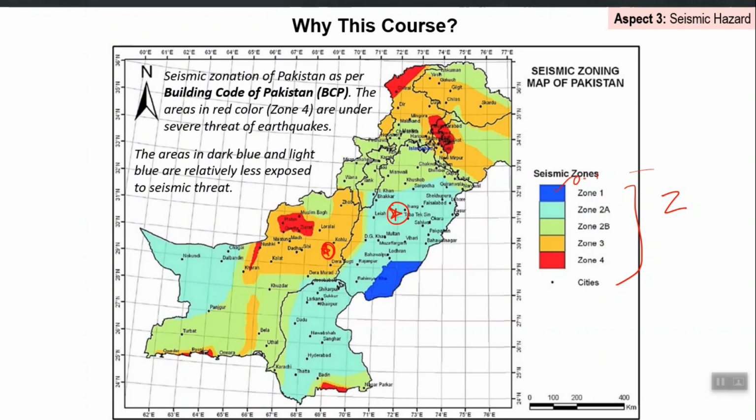So you will have a clear picture, and ideally your point is correct that we need that historical data. That whole process is based on the processing of historical data, which becomes the basis for future forecast. If you simply correlate this map with the faults and all the seismotectonic features, you can guess that there will be a fault here, and a fault here, because all the historical seismicity we convert into future forecast, after all that statistical analysis in a probabilistic framework, right. So I'll give you an overview of the PSHA process also, right.